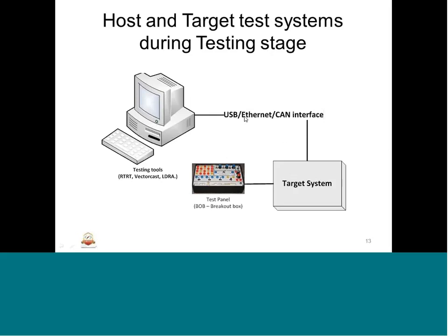We use interfaces such as CAN, Ethernet, or it could be RS-232 also. I have seen a separate system connected to the target system, I mean a separate interface as well. Some of the monitoring can be done with the help of that. For example, RS-232, and that all can be segregated in the host with the help of something like testing tools. Those testing tools will help the user identify the failures or run scripts and batches, etc.